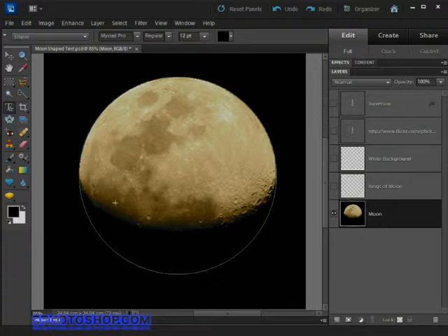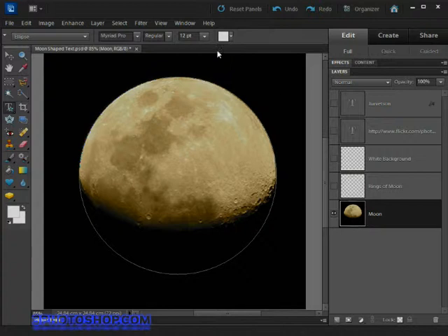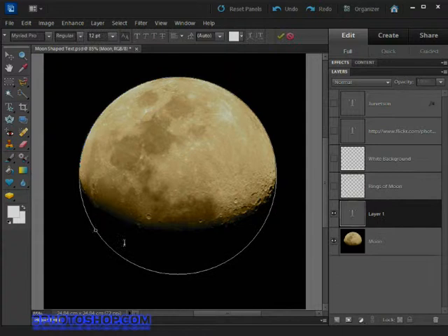Now before we click, we'll want to change the color of the text by coming up to this swatch in the options bar and giving the arrow next to the swatch a click. Black text against a black background is never a good thing, so let's change it to white so it stands out pretty nicely, and then we'll press enter here on the PC or return over on the Mac to accept that color modification. Now just to the left side of where we want the text to go, click on the path and we get our blinking insertion cursor.